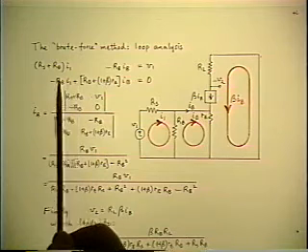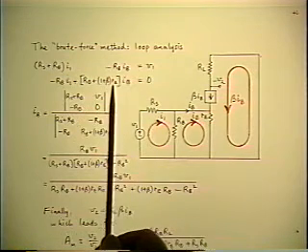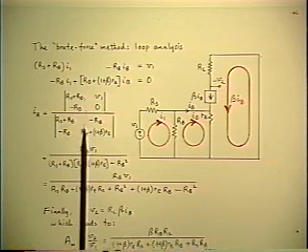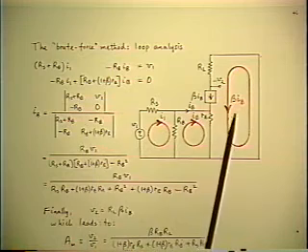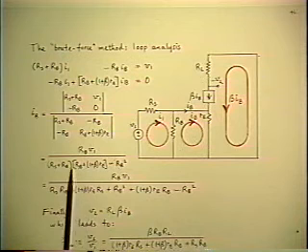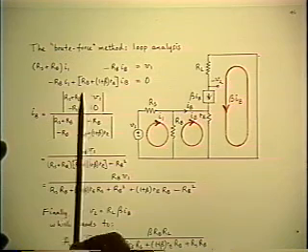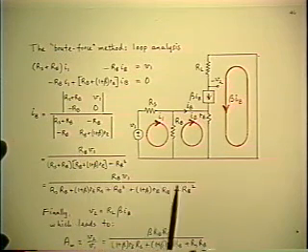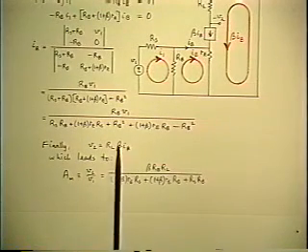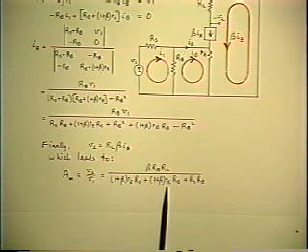So the standard way of doing the analysis is you write the 2 loop expressions, Kirchhoff's laws for each loop, for which the solution for the base current is a ratio of 2 determinants. One more step now, multiply the IB by beta by RL, gives you finally the midband gain of the circuit. Solving the ratio of 2 determinants gives you this intermediate expression, and then substituting into the final expression, multiplying by beta RL, gives you the final result.